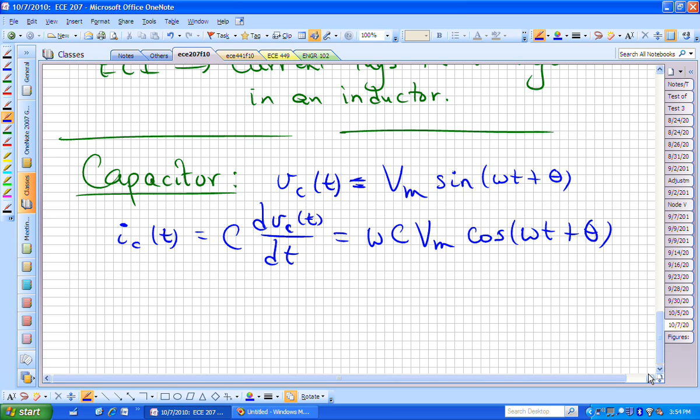And that's just ICE. If we now do exactly the same steps that we did before, and I'll put the bar over it, we now want to go into the frequency domain. We're now in the frequency domain. And you need to remember where you're at. You're either in the time domain or frequency domain. And why are we going to the frequency domain? So we can do algebra instead of differential equations. Yes. Woo!